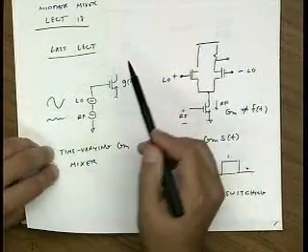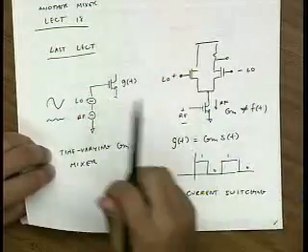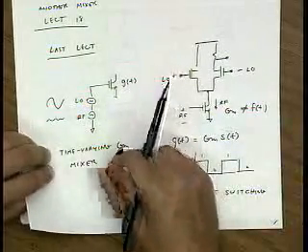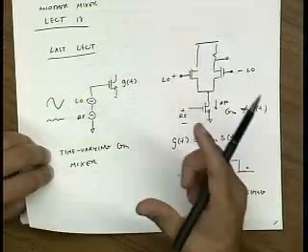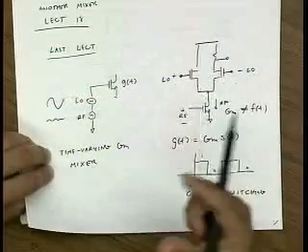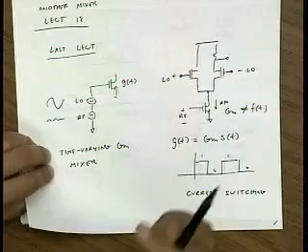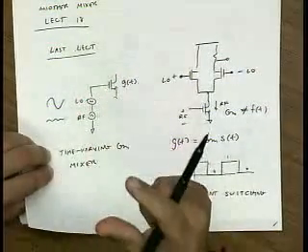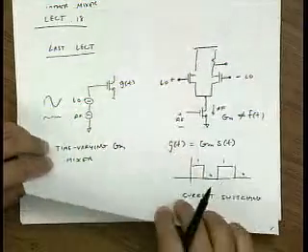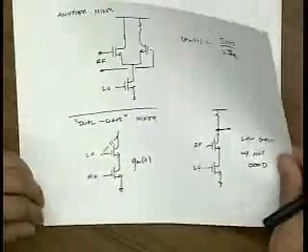Okay? Now, LO leakage, why is that bad? Well, usually the next stage after the mixer could be another amplifier, or it could be an A to D converter. And if you have a large LO swing going into that A to D converter, basically you could completely clip the next stage. It could overwhelm the signal because its strength could be a lot larger than the RF converted signal. So it's much better if we could get rid of that LO. Similar argument applies for RF.